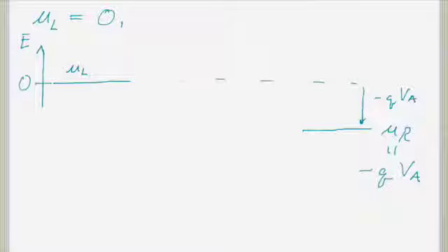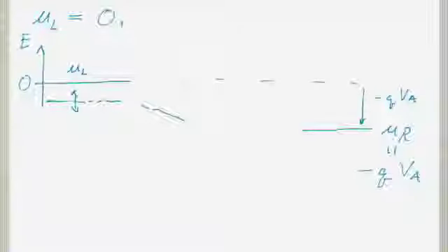And then you just send this into Poisson's equation, and because it forces a zero field boundary condition, right? The electric field is a derivative of the potential. A zero field boundary condition. And the zero field boundary condition enforces charge neutrality in the leads. So over here in the leads, this thing is automatically going to float until it finds its happy charge neutral region. And the same thing happens over here.